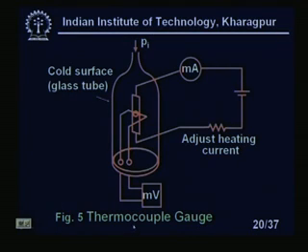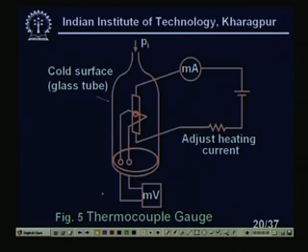Now, this thermocouple gauge has a quite fast response time. Even though the principle is slightly different, its response time, if you compare with the Pirani gauge, is much less. The basic principle is also based on thermal conductivity. There are gas molecules, and these gas molecules will try to take away heat from a heated filament. We are heating this filament with some battery, or rather a heated plate. The principle is the same; instead of a coil I am using a heated plate, so this will be heated.